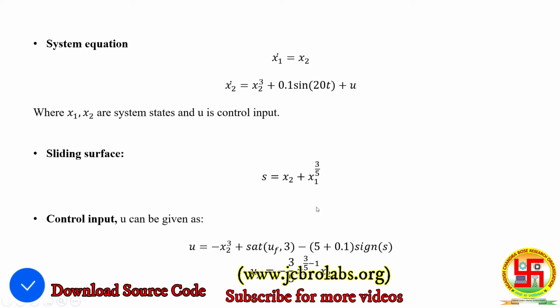Basically, when we differentiate this sliding surface, we can get this function also, but we are taking saturation of it, so as to avoid a singularity problem in our control technique. Now we will design a Matlab simulation diagram for the same system equation, sliding surface and control input, and for the reference we have linked the reference paper in which this whole system, sliding surface and control input is presented similarly.